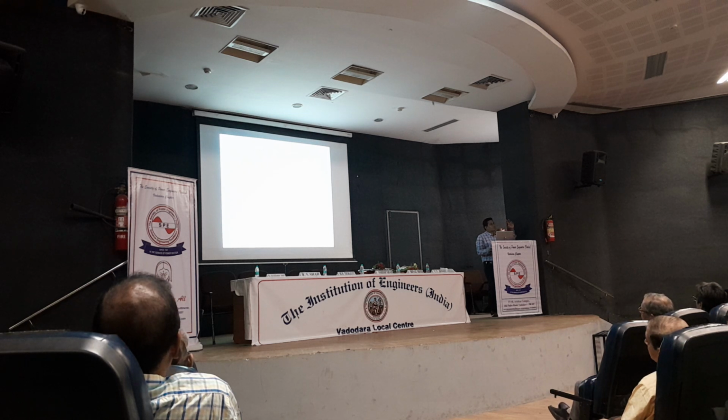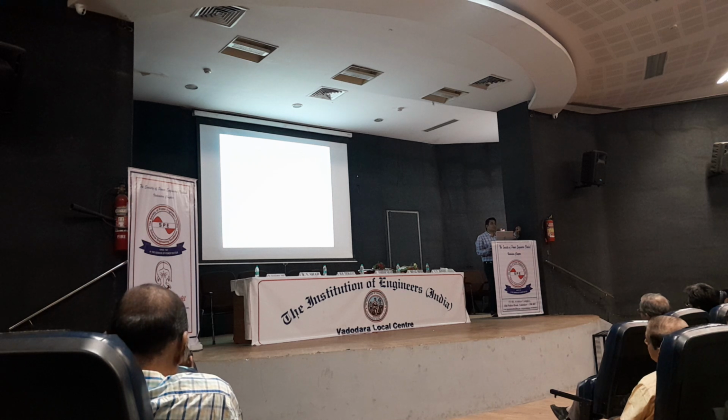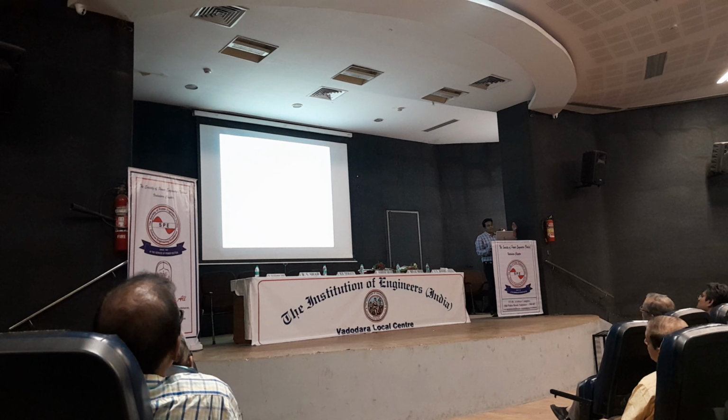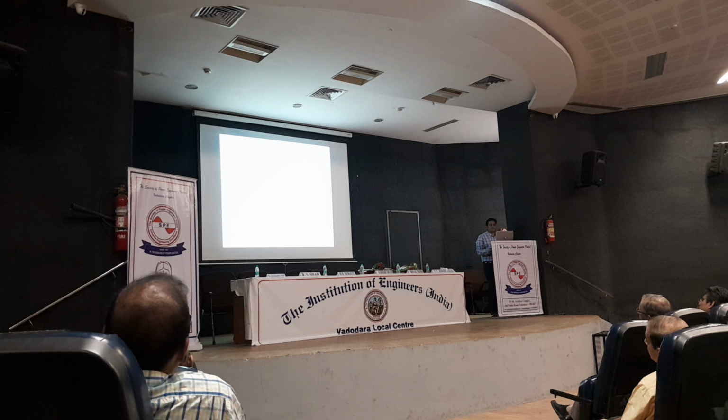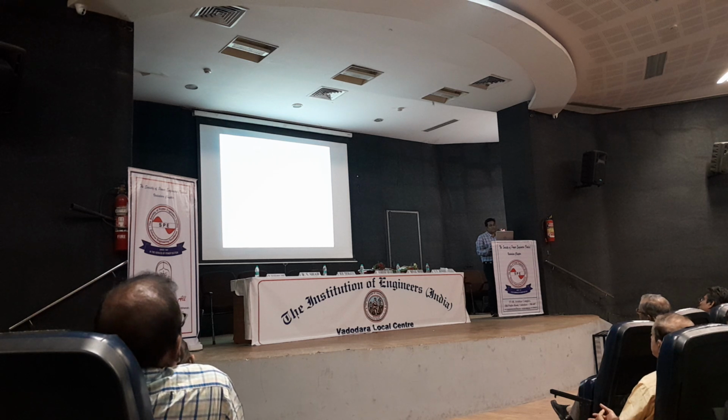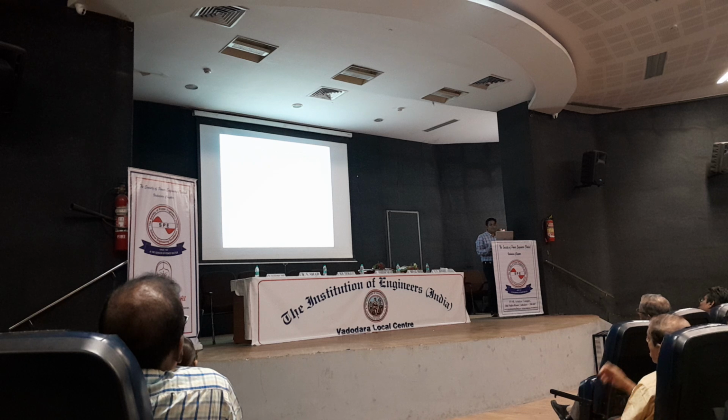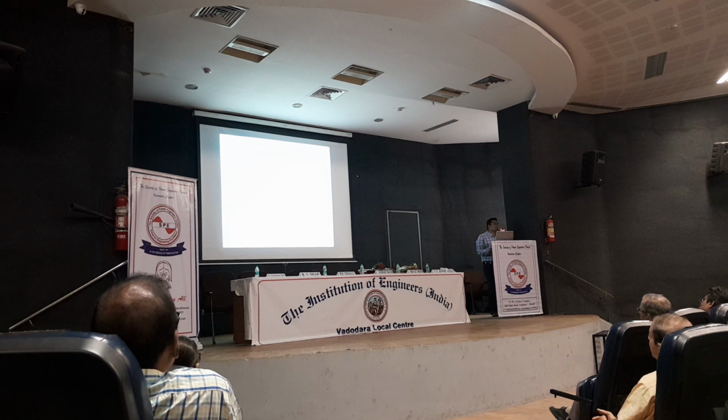So the beauty is that you are investing less time in your analysis compared to other software packages. You do not need to summarize everything or calculate each and everything. Direct summary is possible. So you have the 165 megawatt connected load, 169.56 megawatt is being generated, that is power generated, 4.59 megawatt that will be the active power loss, minus 17.43 megawatt ampere reactive, that is reactive power loss.